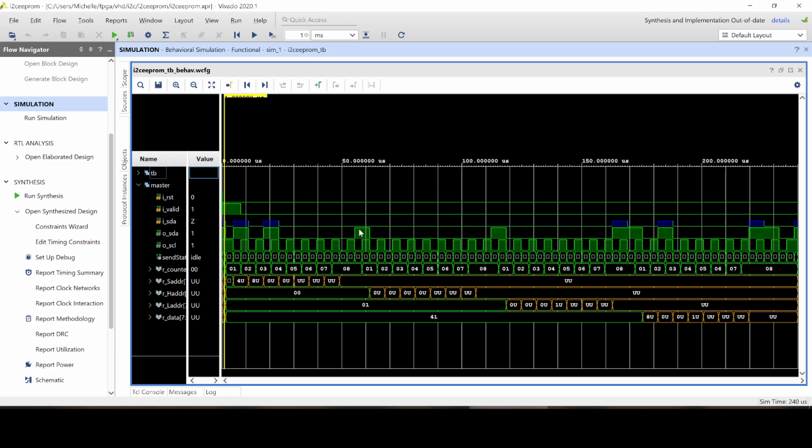Now, whenever I'm in the high SDA, remember, I told you it had to be in the high, it goes to high impedance. I need to get a low clock data. And so while this is high and this is my actual clock, I'm getting a low data. So that's where my acknowledgement is actually happening right here.